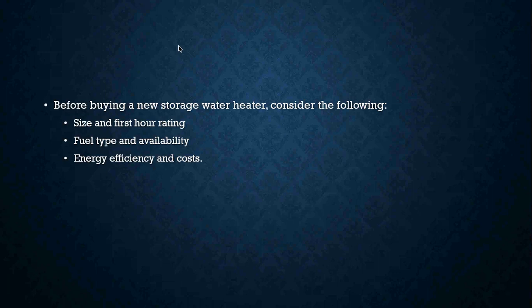Before buying a new water heater, you want to consider the following. Okay, the size and again the first hour rating at which that water heater is going to be worked. Remember, day, morning, afternoon, evening. When is that first hour rating highest peak going to be? Your fuel type, is it gas, is it oil, is it electric, is it propane? Okay? And obviously the availability of those heat sources.